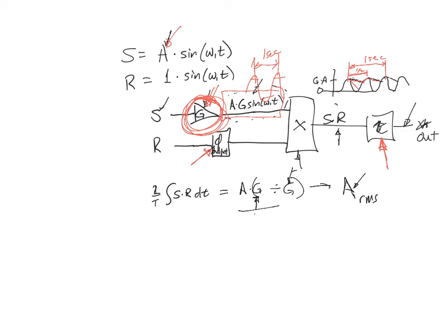So if we're setting the time constant, we need to know what frequency we're going to be looking for. What is this omega 1? If it's a kilohertz, then you need a time constant that's long compared to, say, a millisecond. But 30 milliseconds might be fine, or 300 milliseconds might be fine. That's one bound. In other words, if you're doing a 1 kilohertz measurement, you do not want to set the time constant to be 1 millisecond. That'd be ridiculous. On the other hand, if you set the time constant too long, and then you change something in your experiment, so you change that resistance, then the output here can't respond much faster than this time constant.